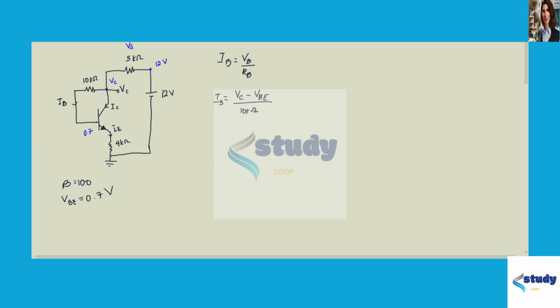So we have an unknown here, which is the voltage at node C. We could get this from the equation of voltage division, or that is VC is equal to VCC, or our voltage source, minus the voltage in the 5 kilo ohm resistor. So 12 volts minus the voltage in the 5 kilo ohm resistor will give you the voltage at node C. But what is the voltage across the 5 kilo ohm resistor?